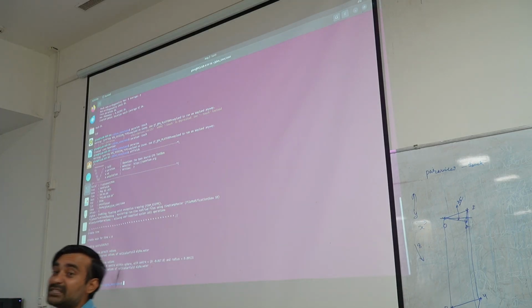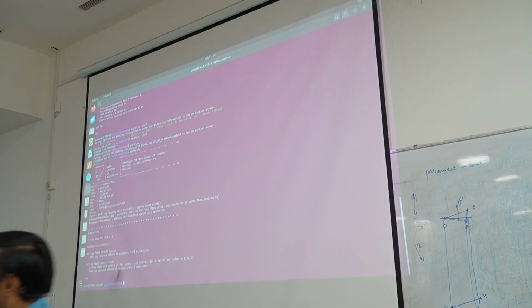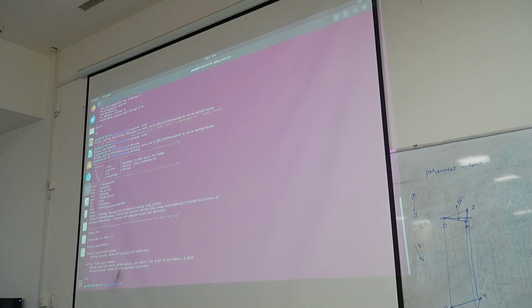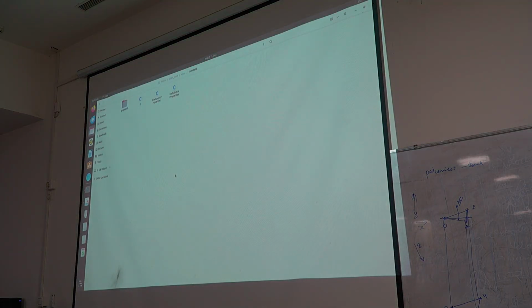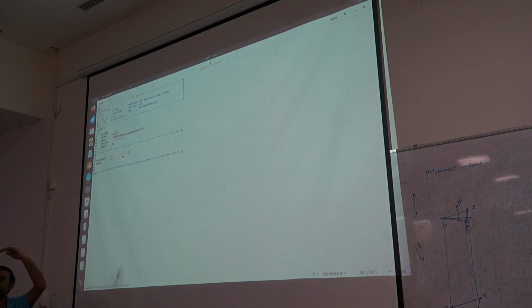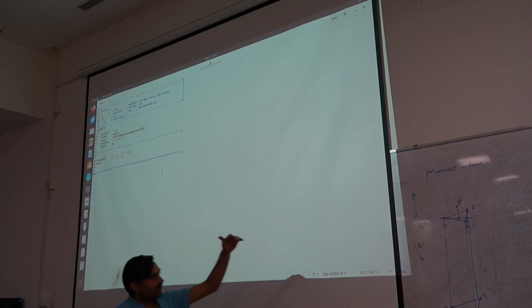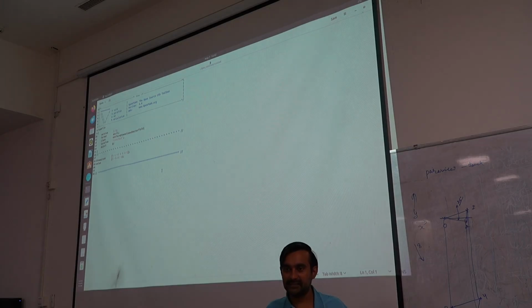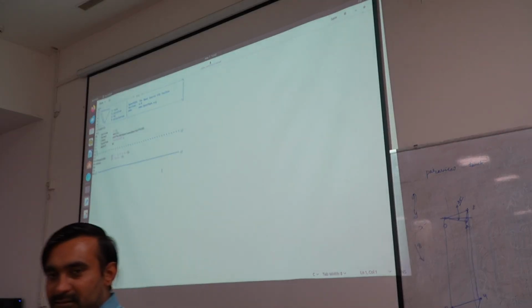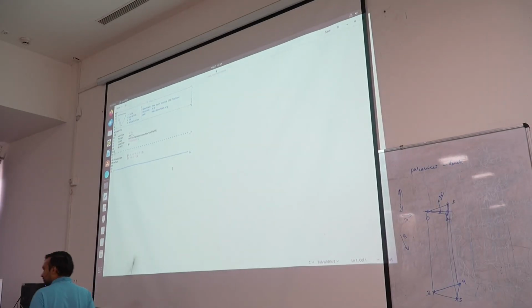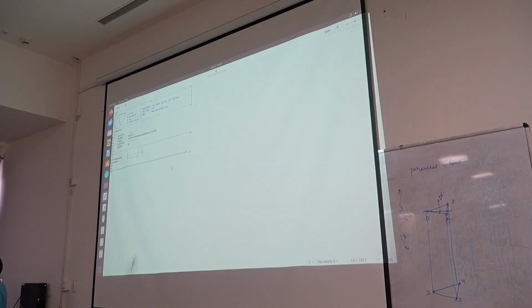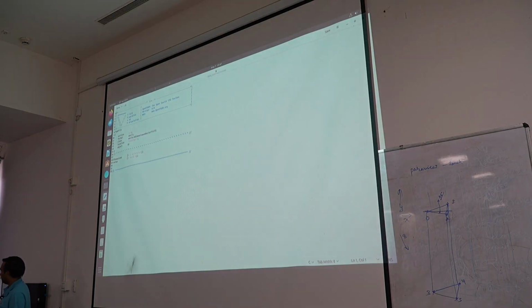Before that, we need to specify properties. For specifying properties, we will go to the constant folder. In the constant folder, I need to define gravity. You can see gravity is in which direction? The y direction, and the negative y direction. So I must write minus 9.81 in the center, because this is a vector field.